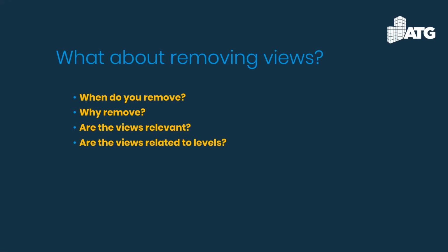And if you got a starter project that has more levels than you actually need, you may want to go in and just delete those levels out that you're not going to use. And it's going to go in and remove those views from your project. It will ask you if you want to remove those. So it's not going to do them automatically. It's just going to ask you, do you want to remove these? Are you sure you want to remove them? Click yes, and it's going to remove them out of that particular project.